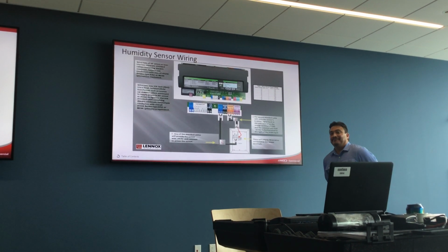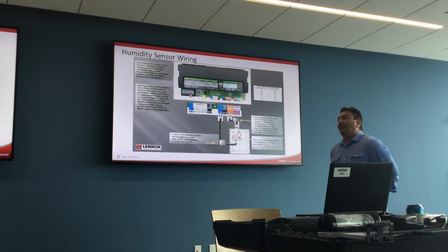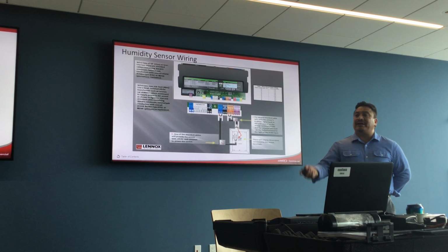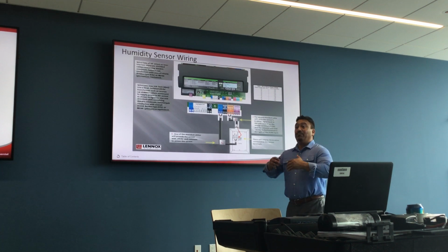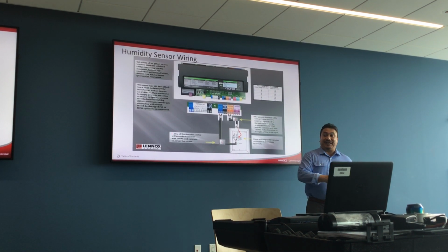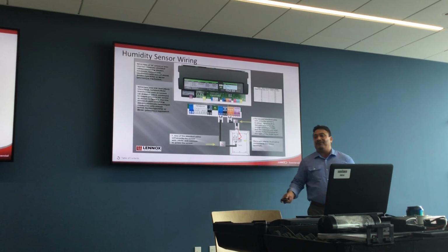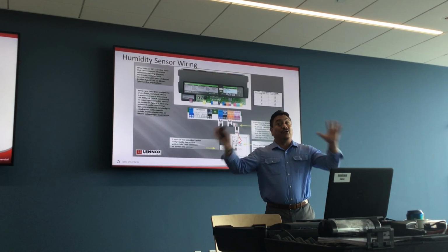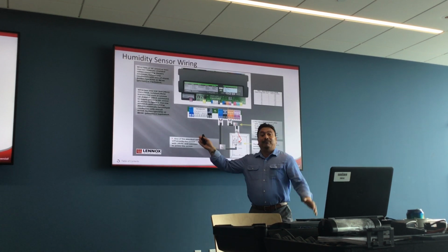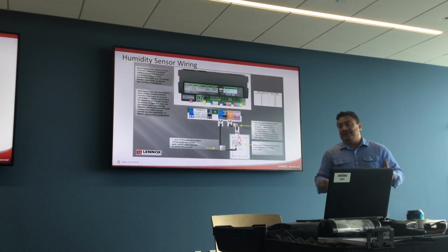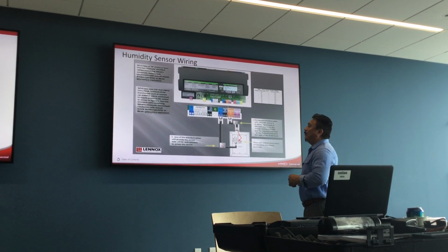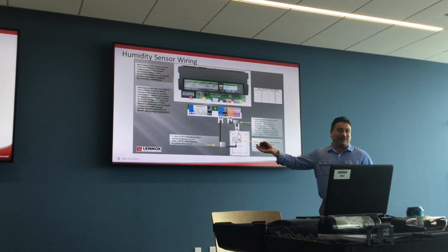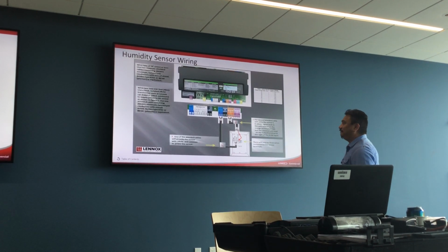They never pull wire. We can get that from Granger, right? Belden wire? Shielded wire? Belden wire is probably the most universally recognized low voltage wire manufacturer in the world. Like Belimo, everyone loves Belimo, but there are other manufacturers that actually make parts. Belimo would have you believing they are the greatest ever and don't think of anybody else. Belden is the same way, so we took that into consideration and inputted their name into our slides. But they're not the only manufacturer of shielded cable, guys. As long as it's 20 gauge.